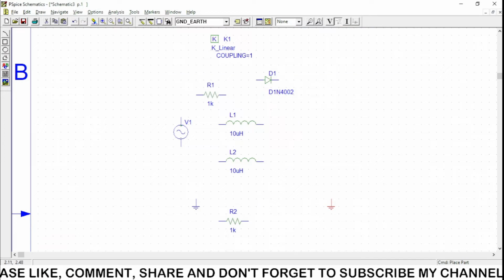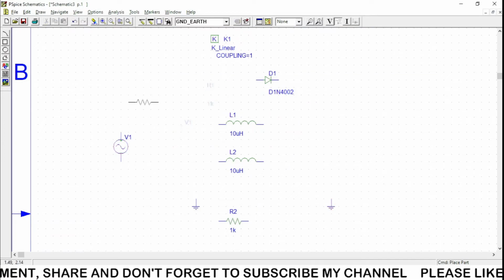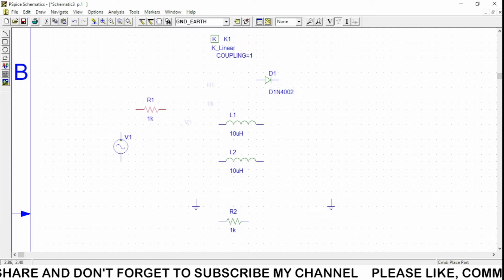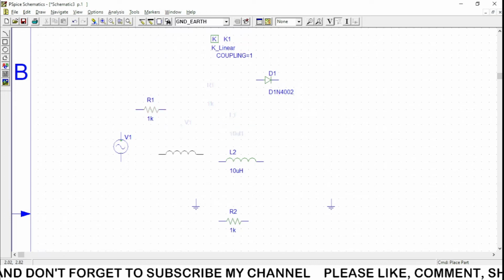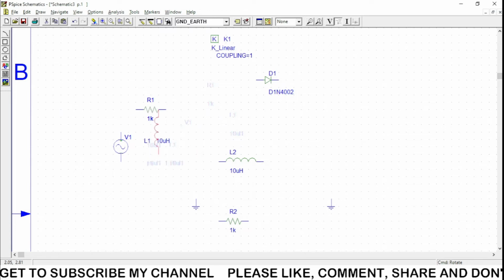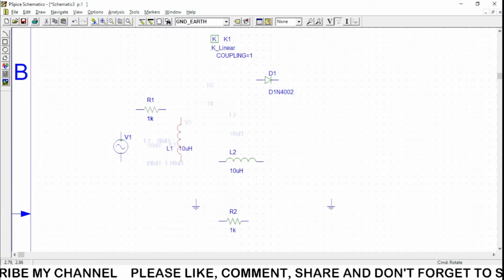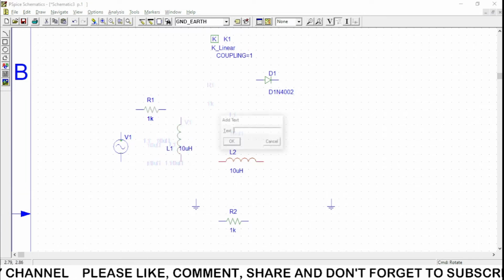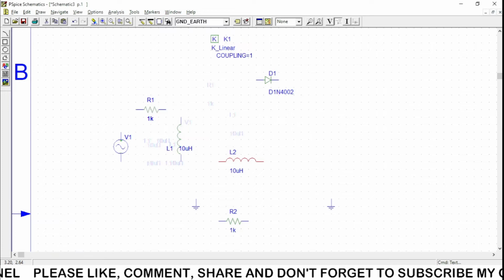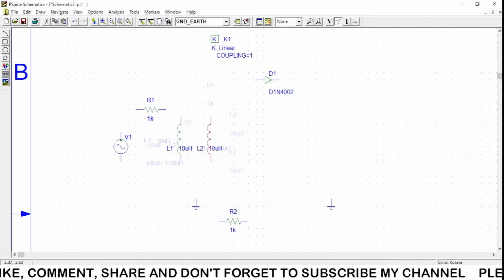Okay, so here we can place the V sine source. Resistance R is needed to prevent the inductor from going into a loop. Here is an inductor. I am going to rotate it, so we are going to rotate it like this. This is the way we can connect it. This inductor we need to form a transformer. So I am going to rotate it again. So this is the transformer now.